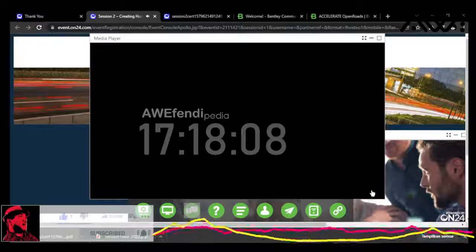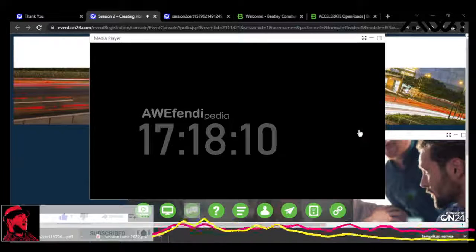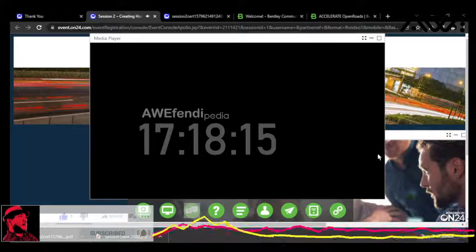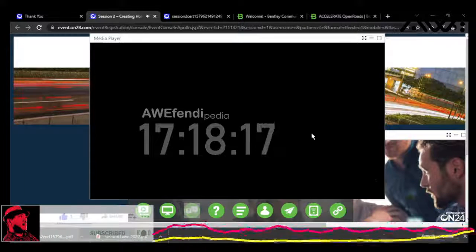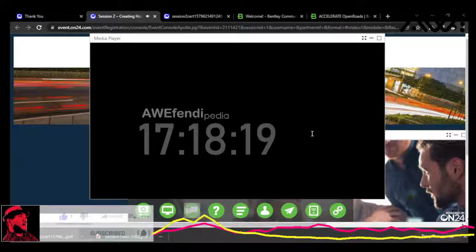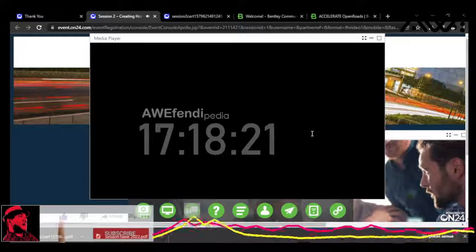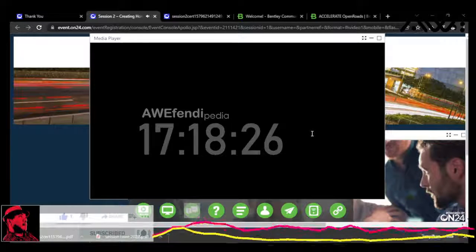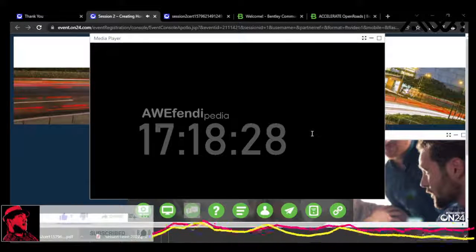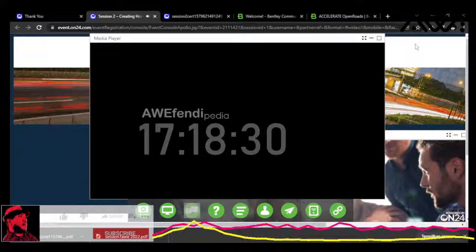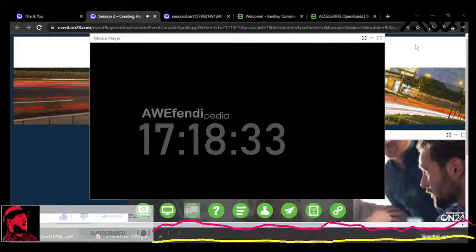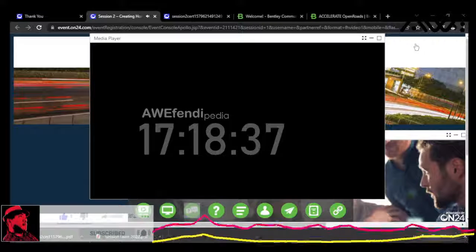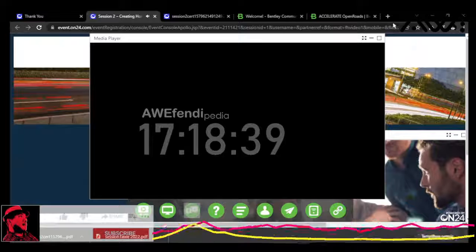Now, in terms of that as well, what do we know about this alignment? And I did this. This is in your data set as well. There's a PDF file that represents the existing horizontal alignment, and we're going to use this as the basis from which to create our horizontal centerline for Highway 72. So here's the output. This could appear in the real world on a set of old drawings that you have. Again, this could be in a report. This could be in different places, but we're going to take this as the known horizontal geometry, and we're going to begin constructing that geometry.